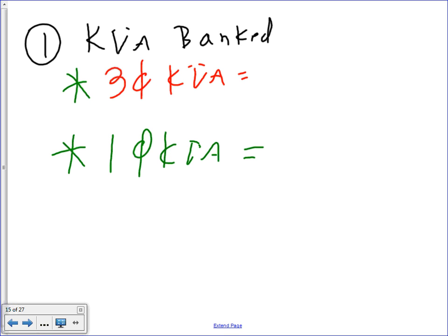Not derated. No, you're talking about derating open delta. I think you're confused with open delta. This is not an open delta. Is this an open delta? This is a closed delta center tap. There is a C phase, but the transformer is between C and B.